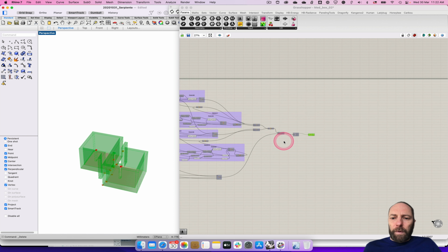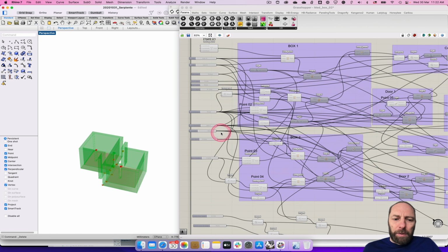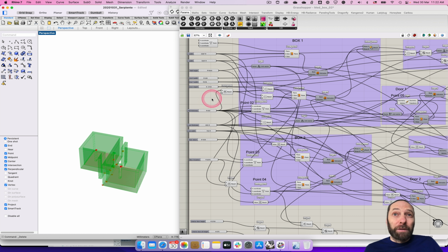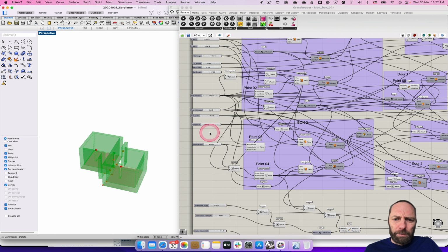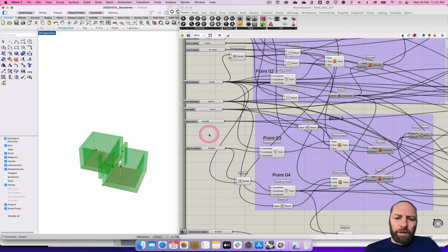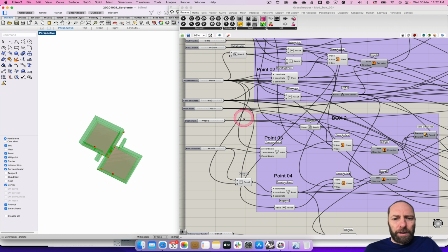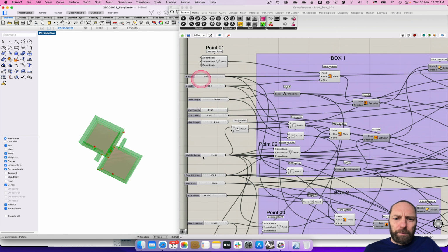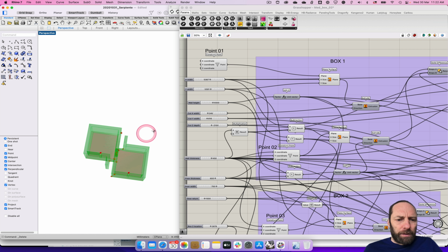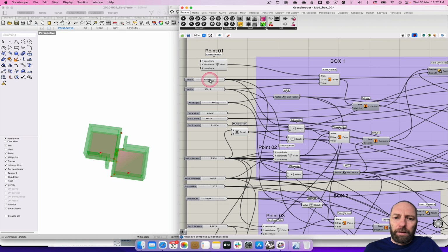And then the main part of this was going to be to quickly make some adjustments. The benefit of doing parametric design is that it has allowed us to quickly modify and change everything without having to go back and remodel and almost go back to square one sometimes. So I'm just going to play and see what happens. Let's make, if we go into that view, so X is across and Y. Let's make X a little bit thinner, so it comes in quite narrow.